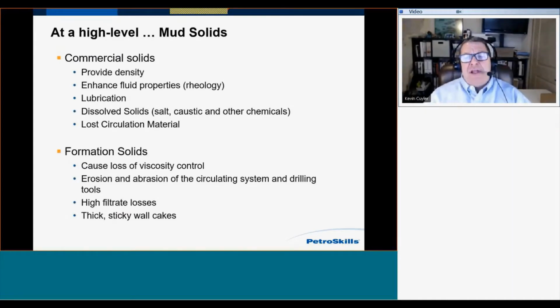So we basically look at solids and we say, okay, is it a commercial solid or is it a formation solid? Today during this webinar, when I use the word commercial solid, I am talking about a solid that we intentionally put into the drilling fluid and add to accomplish a purpose. Somebody is paying to put those solids into the fluid.